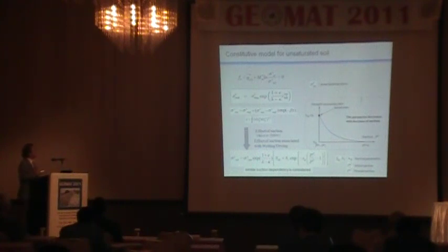It is controlled by the accumulated plastic strain, so it is decreasing and also increasing, depending on the material parameters sigma_m, k, f, and beta. It shrinks or expands. And I also consider the effect of suction. This term exhibits the effect of suction.